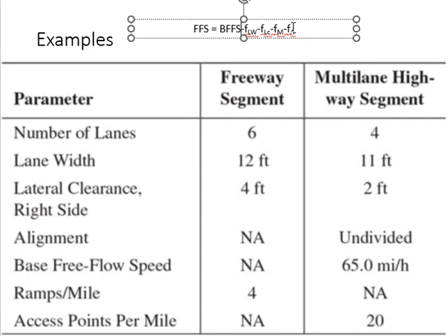Okay, last column. Which value from the last column can go into the equation? The base free flow speed. What is the base free flow speed? It is the maximum speed, the design speed. Base free flow speed means the maximum speed, the design speed. If you are doing it for a highway which will be designed in future, you will pick your design speed. So this value is given, I can replace it with 65.